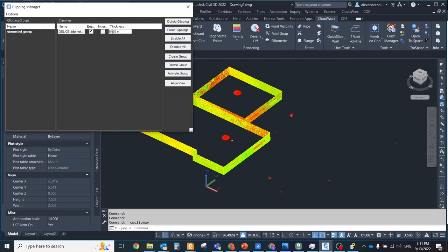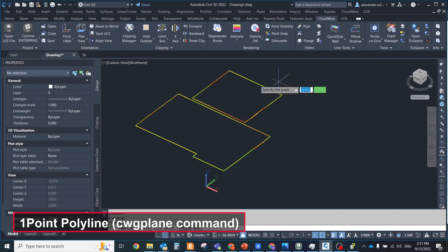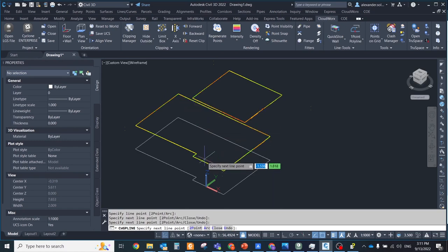Next, you have two options for fitting polylines into the section of point clouds directly on the main screen. 1 point polyline: draw an auto-fit line string with 1 point grow line segments. Each line segment expects one pick point and will region grow to find the best next line for the point cloud. Each line segment will connect to the previous one as it is created.